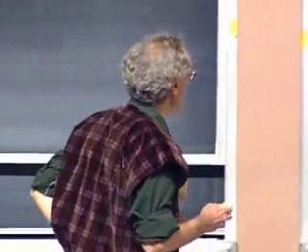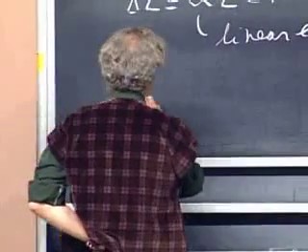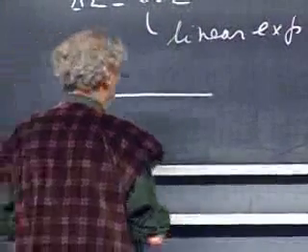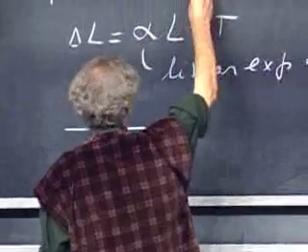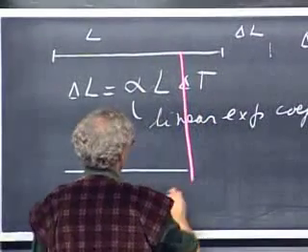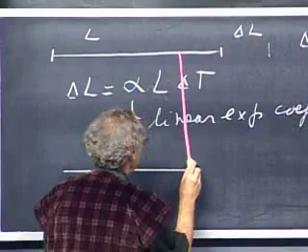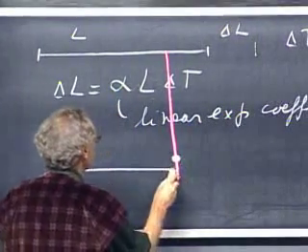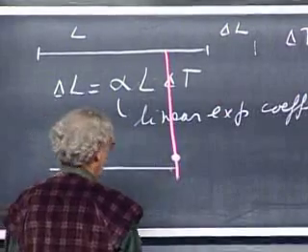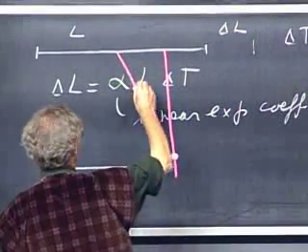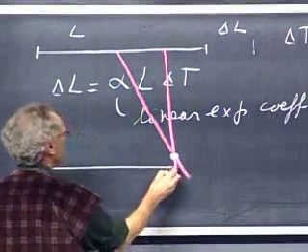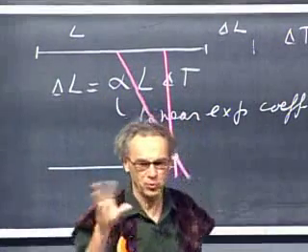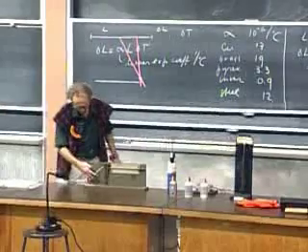The way we do that is we have some kind of an amplifier. If this is the rod, and I would put here a hand, and pivot that hand here, then it's easy to see that if you push against it here, this hand will go like this. So very little extension here will give you a large extension there. We do it twice, so we have 2 levels. And that is this arm.